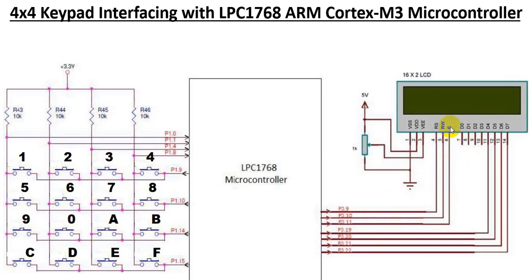The third signal is the enable signal. Now what is the role of this? This signal will make sure whatever the command or the data which you have sent is written onto the LCD. So if you make enable high to low, then whatever the command or data which is sent via these port pins will be registered in the registers of the LCD.